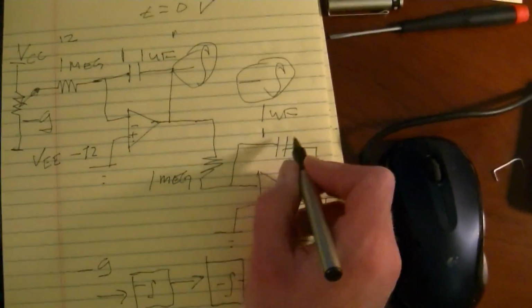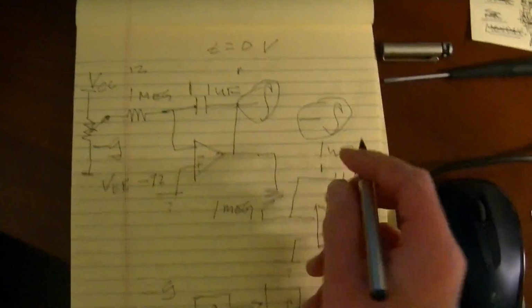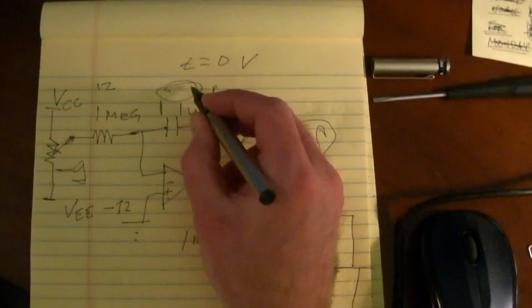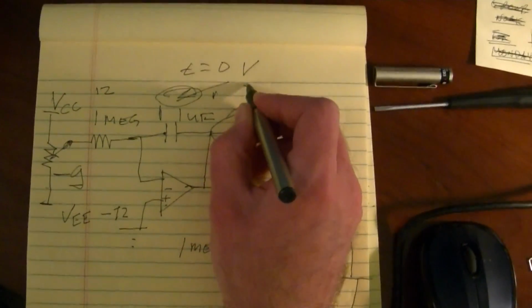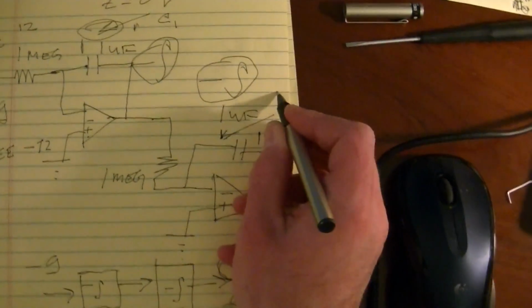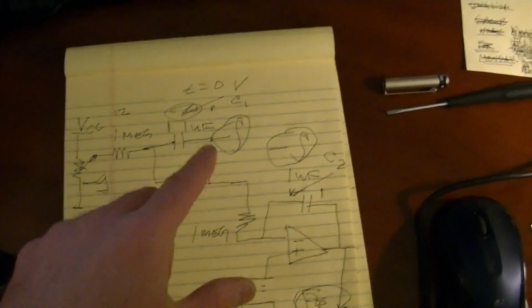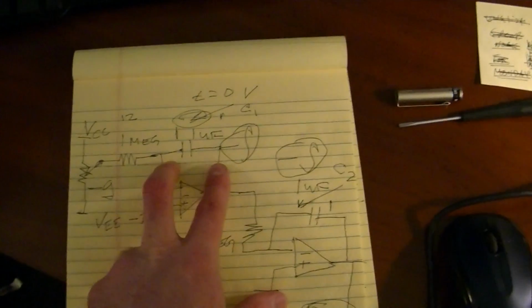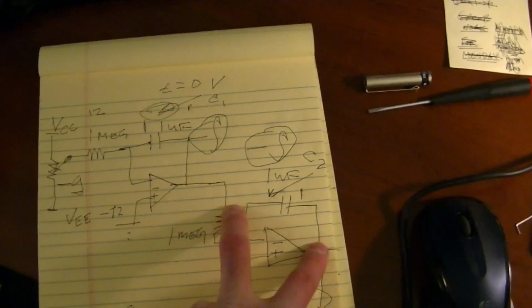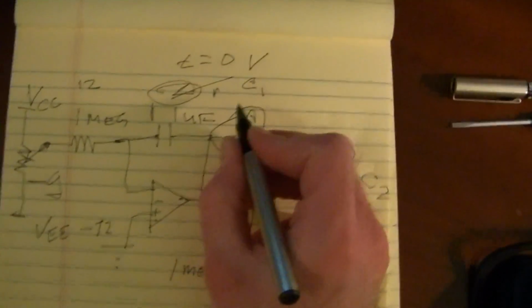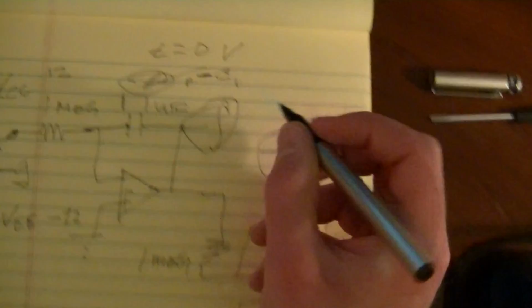And actually, the voltage constant, which is provided by the two relays I've shown in the circuit, this voltage here at t equals 0 is related to C1, and this voltage here is related to C2, which are respectively initial position and initial velocity. Considering this is an inverting integrator and this is inverting that, this would be negative the value of C1, which is applied across this capacitor for just a moment.